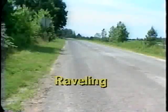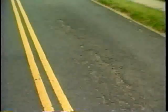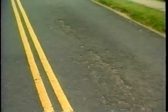Raveling. Raveling is a loss of aggregate from the surface layer of the pavement. It can be caused by the hardening of the liquid asphalt, poor application techniques, or an insufficient quantity of residual asphalt. This condition is most common on existing asphalt chip seals that are several years old.